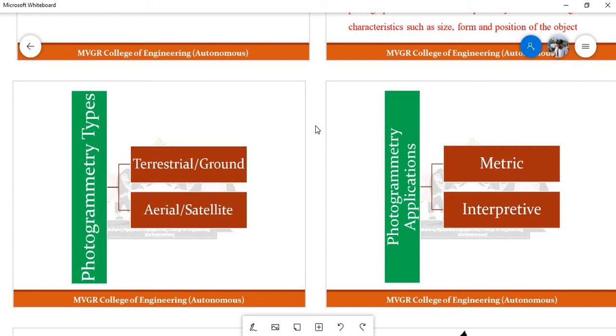If you see the photogrammetry applications, we have discussed these things also: metric photogrammetry and interpretive photogrammetry. Metric, again from the name itself, metric means measure. That means from the photograph we will measure some quantities like height of a tower, distance between 2 points, length of the road, length of a road line, kind of things.